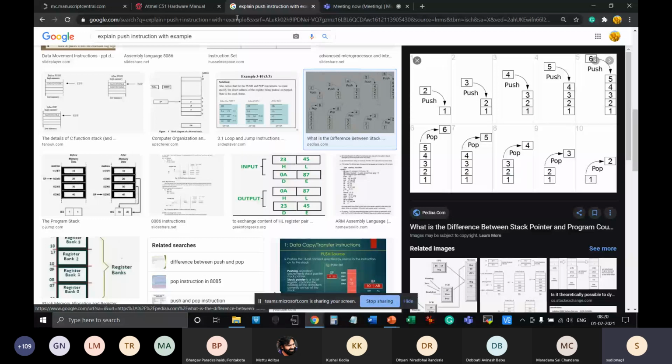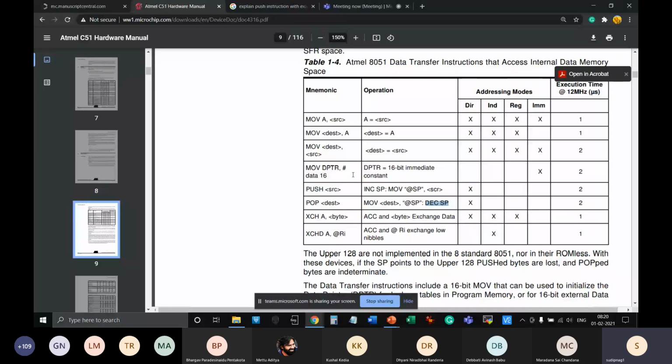This is a sort of rule in programming, because otherwise you can keep losing data if you have an unequal number of push and pop instructions. So one push should be followed by one pop. If you apply 2 push instructions, then 2 pop instructions should come, and so on. We'll see examples as we go to programming.